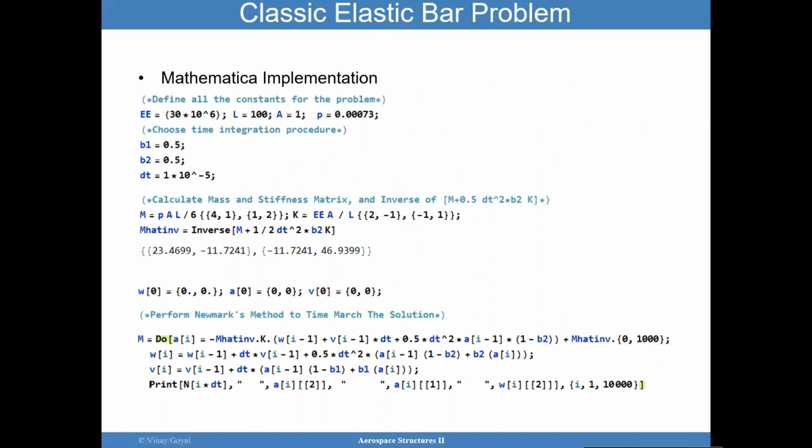This was done in Mathematica. My purpose today is not to teach you Mathematica, but why don't you go ahead and pause the video and see how I went about it. In fact, go ahead and see if you can even program it in a different program like MATLAB, and basically time march the solution. I have a do loop here that basically runs through the Newmark beta method and solves for the deflections, accelerations, and velocities as a function of time.